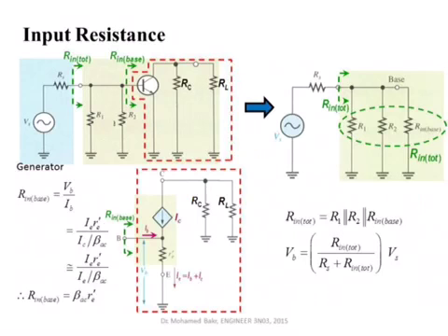Okay, we'll start first by calculating the input resistance. So we already did the DC analysis. We know what RE dash is. We know the model. We know how the AC model looks like. And this is my AC circuit. Okay, as I mentioned before, RC is in parallel with RL. R1 and R2 will be parallel with one another. And the coupling capacitor is short circuit. RE was shorted out by the bypass capacitor. There was another coupling capacitor here. It became short circuit.